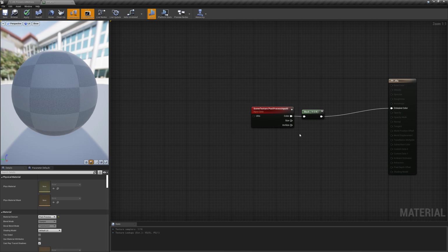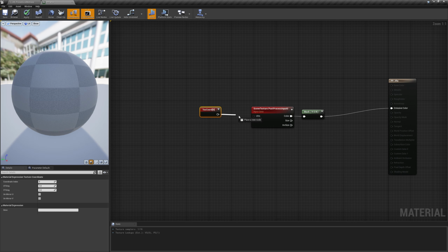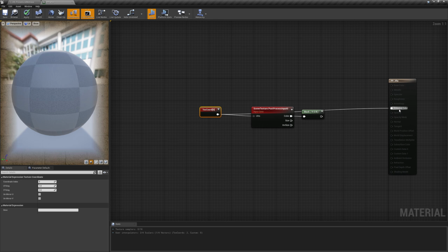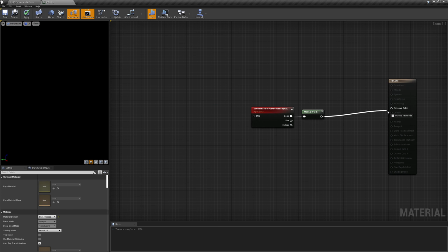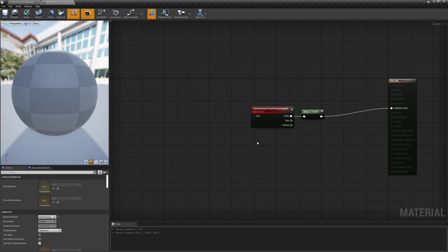Notice that in this node is available an input pin for the UV coordinates. In this case though, those coordinates are not coming from some mesh UV mapping, but contain each viewport pixel position divided by the viewport width and height. By noticing that, we can understand that all the image distortion operations will be placed before this node, while all the color manipulation ones will be done after.